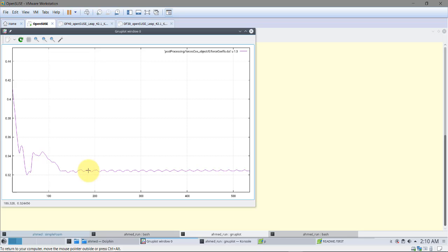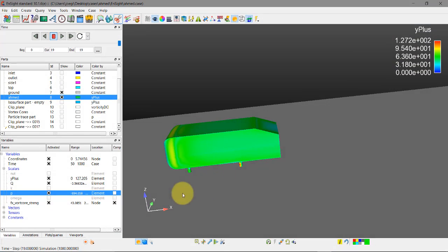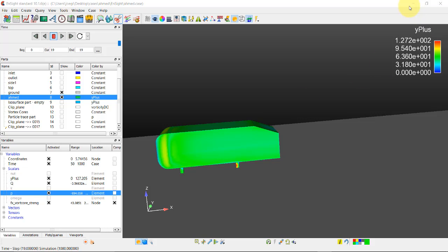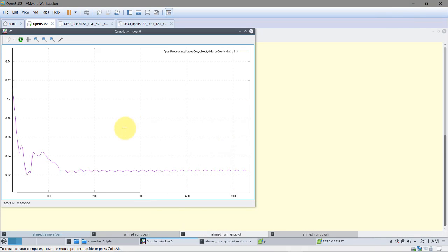So check your drawings, go to the original drawings, and you will see that there is a difference in the steels in the support, but also the slant angle, the angle in the rear of this body. Okay, we're using an angle, if I recall, of 20 degrees. In the actual papers, most of the papers use 25, 35, or 30 degrees. So the results won't be 100% accurate, but we're in the ballpark. Those are the results that we have. This case is not meant to be a proper validation case, just to keep things running.